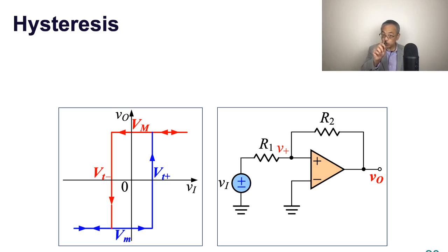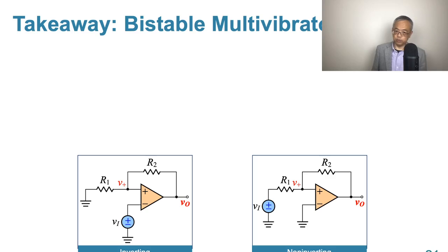All right, so the arrow is important. I said this in the previous lecture: today's behavior depends on the history, on where you come from. You come from the rest state with VI going down, or you come from the blue state with VI going up, if VI is located between the two threshold voltages, in the hysteresis window.